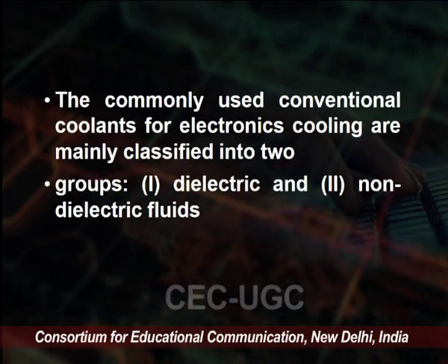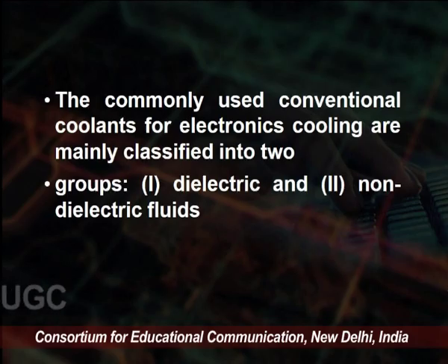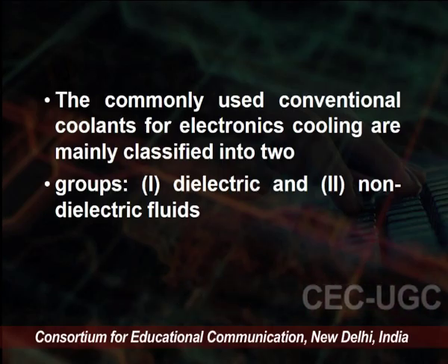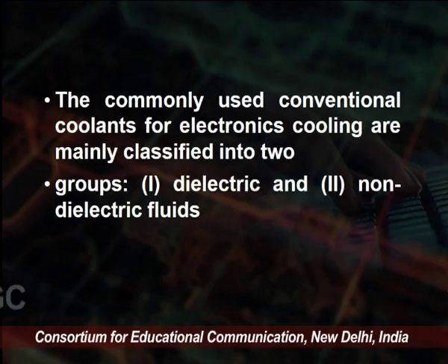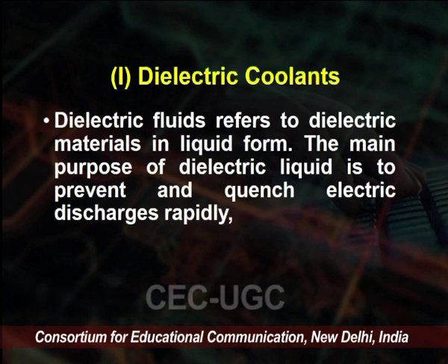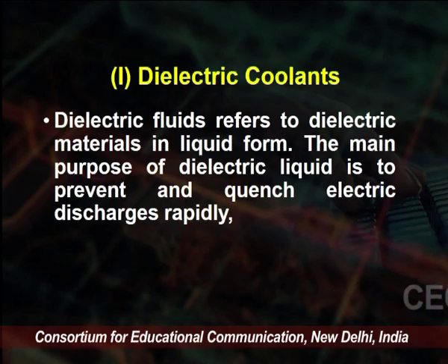So commonly used conventional coolants for electronics are classified into two categories. First is the dielectric, second is the non-dielectric coolants, or we can say dielectric fluid or non-dielectric fluid. First is the dielectric coolant. Dielectric fluids refer to dielectric material in liquid form. Dielectric materials we can take, but it must be in liquid form that we can use. The main purpose of the dielectric liquid is to prevent and quench electric discharges rapidly.